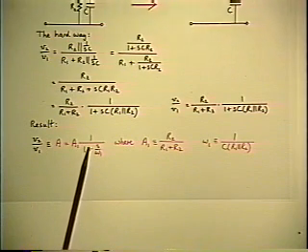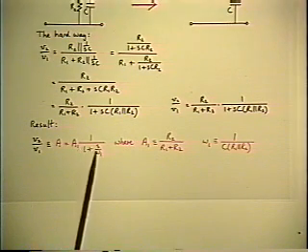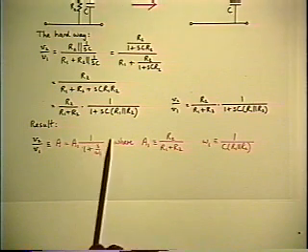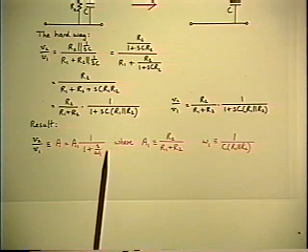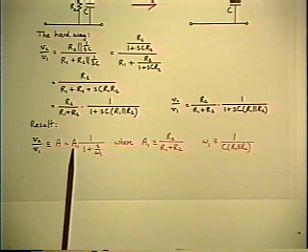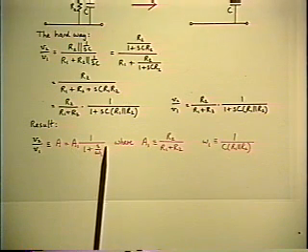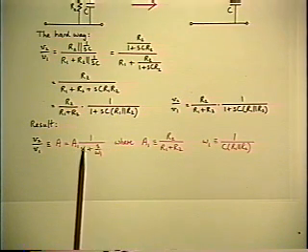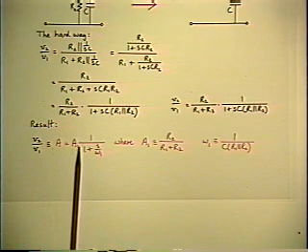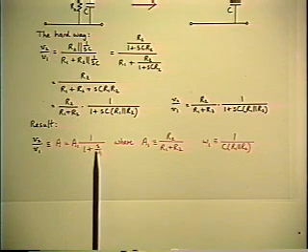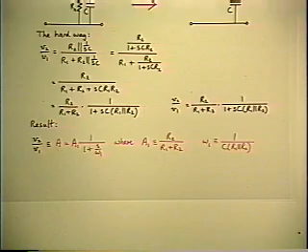So this is the normalized format, which is a simple case of expressing the frequency response in factored pole zero format. In this case, there are no zeros and there's one pole. And the coefficient in front is a flat gain. In this case, the flat gain is equivalent to the zero frequency gain. Because if you let S go to 0, the other factor goes to 1, so the gain approaches A1 at 0 frequency. So this is the basic building block known as a single pole transfer function.